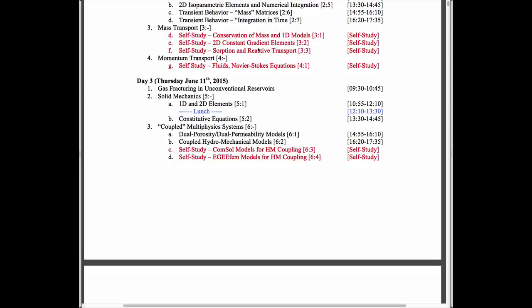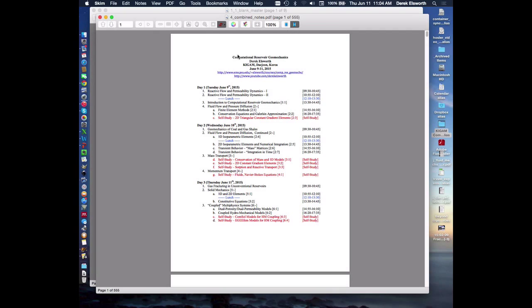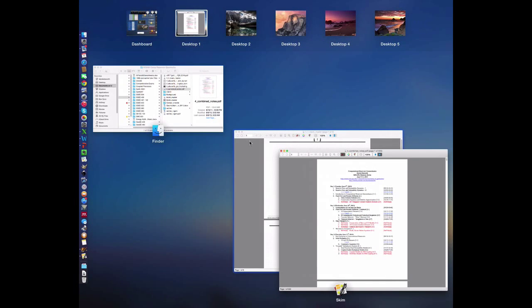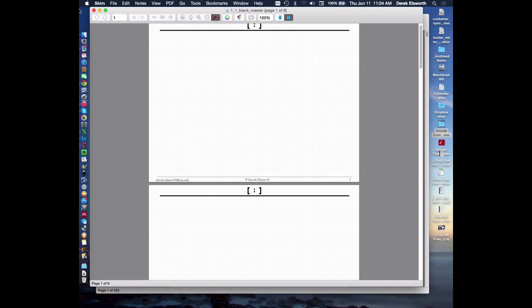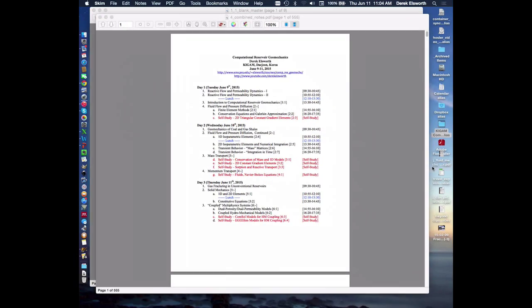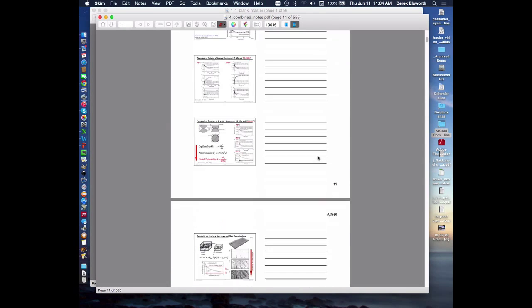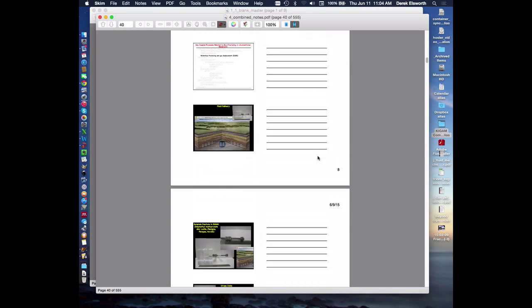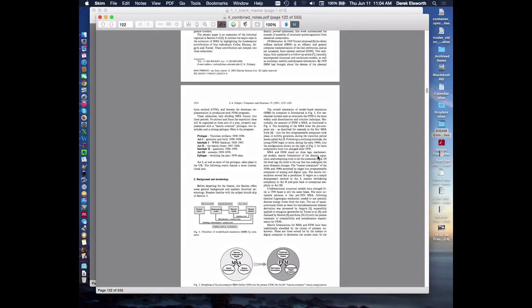And this strain, of course, is equal to a change in displacement with x, the same as this. And so when we look at these expressions, the similarity, which we have talked about, which is perhaps worth looking at, is that all that's different between Navier-Stokes equations and the deformation equations that we deal with for solid mechanics is that they have different constitutive relationships in them.